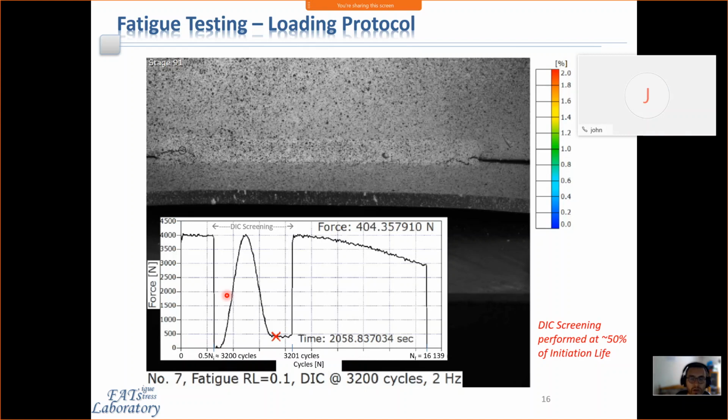May I ask a quick question? Because I don't know if I received the information. Is the filler metal that's being used also 590, or is it a different alloy? It's typically 440. It's a different grade. Okay, that makes more sense than what you were saying, that if the member strengths are a lot lower, then you might see member failure. But if you're using 440 filler metal, then what we're observing here makes sense.